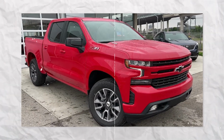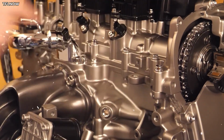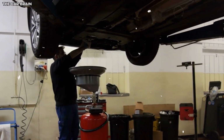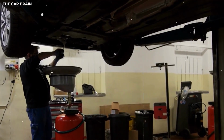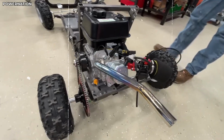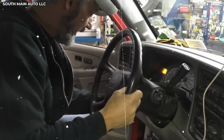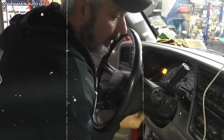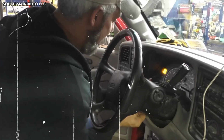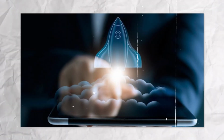Then turn on the headlight switch, even though nothing will illuminate. Open and close the doors several times. You're forcing every last bit of stored electricity out of the system. Leave the battery disconnected for at least 30 minutes. An hour is even better for really stubborn adaptive learning issues, especially on 10-speed transmissions that seem to hold learned data aggressively. During this time, every control module in your vehicle loses power completely and dumps its volatile memory.